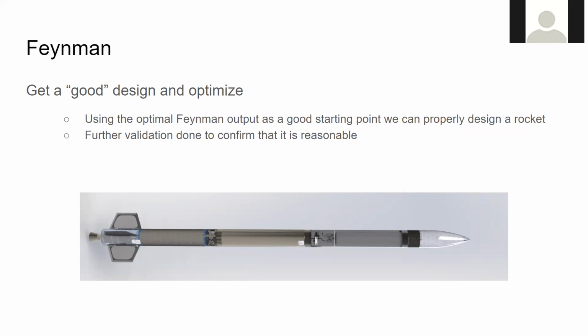Cork is also an ablative, and then there are more exotic ones, like carbon nanotubes and graphite. Basically, any material that has low thermal conductivity, will undergo an energetic reaction, and then fall away.